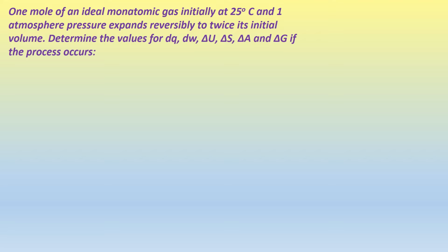Reversibility, once again, requires keeping one variable constant, where the thermodynamic variables are pressure, volume, temperature, and heat. In the previous example, we held heat constant. Now we're going to take the same question. I have 1 mole of an ideal gas, 25 degrees C, 1 atmosphere, with its volume doubling, determining the value of the thermodynamic variables if this process were now to occur adiabatically.